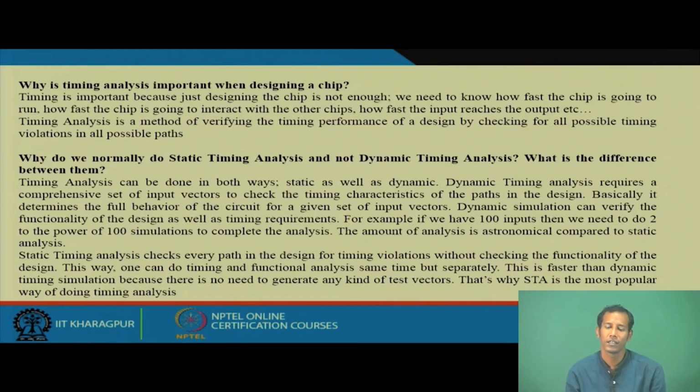In dynamic timing analysis we apply simulation, that means we put in test vectors and check every corner, so that depending on the signal levels, whether 0 or 1, we can analyze the actual circuit performance: if this signal is 0, then it works like this, the delay is this, or the net delay is this. That is an example of dynamic timing analysis.